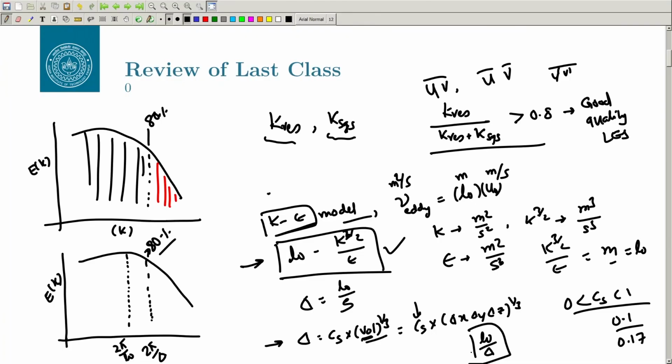Some flows are nominally 3D, that means the third dimension is for the turbulence to develop, but you can have the mean flow in 2D, that means there is no change in the mean flow in the span-wise direction. In that case you can relax the grid size slightly in the span-wise direction compared to what you have in the boundary layer on the face. But if the flow is truly 3 dimensional, then you have to make sure that you are resolving the span-wise direction very well.